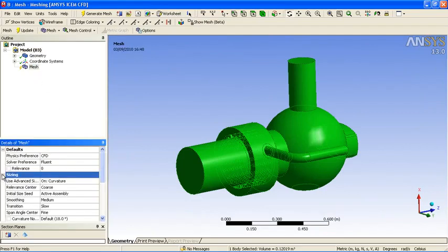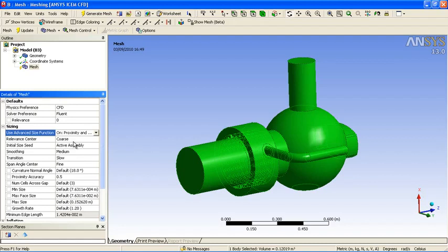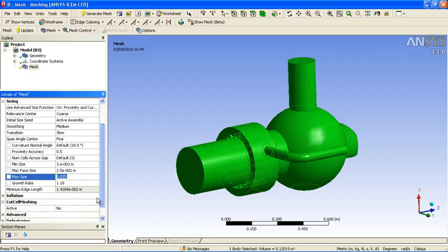So we're going to start in a similar way to the stress analysis model, using minimal user setup and using the automatic methods. In this case, we're going to mesh with proximity and curvature, so this will detect small fillets, especially those small ducts inside the model. We specify minimum and maximum sizes as well as a growth ratio.